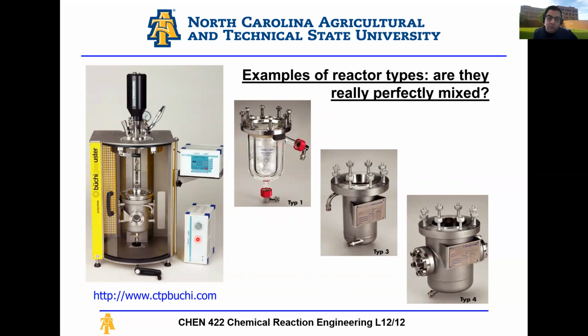So if you measure your concentrations in this reactor here on the left, and you compare it to your ideal CSTR performance equation, you're going to find a difference in the numbers, right? And this difference is not due to the reaction, it's due to your transport non-ideality. So it could be that your heating jacket's heat transfer coefficient actually reduces the heating a bit, and you need better control of your flow rate.